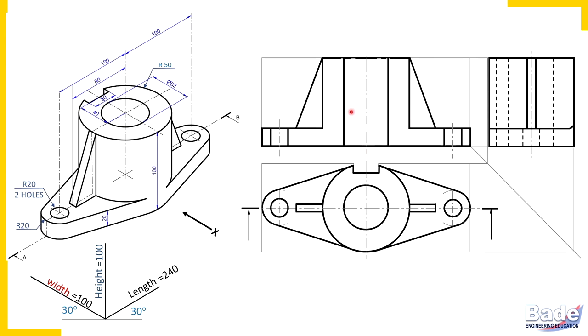No hatching lines here. This rectangle here at the center, that is the inner surface of the hole. It is an original surface which is getting exposed after cutting. It is not a newly generated surface because of cutting of the solid portion of the object. Here the solid portion of the cylinder and the solid portion of the plate get cut. That is why this is a newly generated surface.